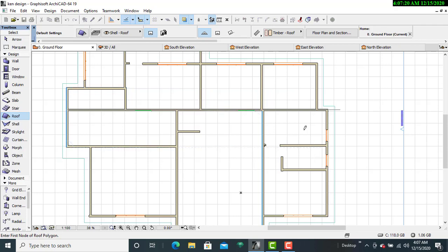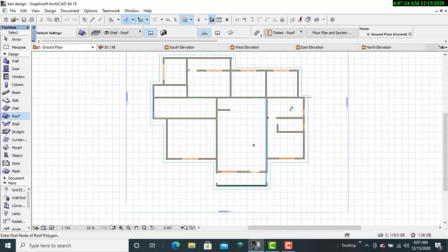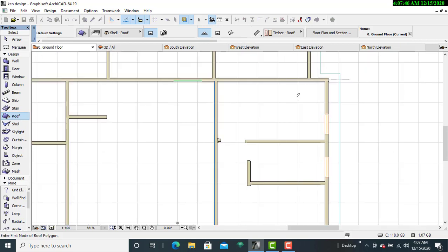Then I'll begin modeling my roof according to the single plane mode. As you can see here, I have my geometry method activated as a single plane, and then the construction method is specified as complete the complex roof. So I believe that is okay for me.